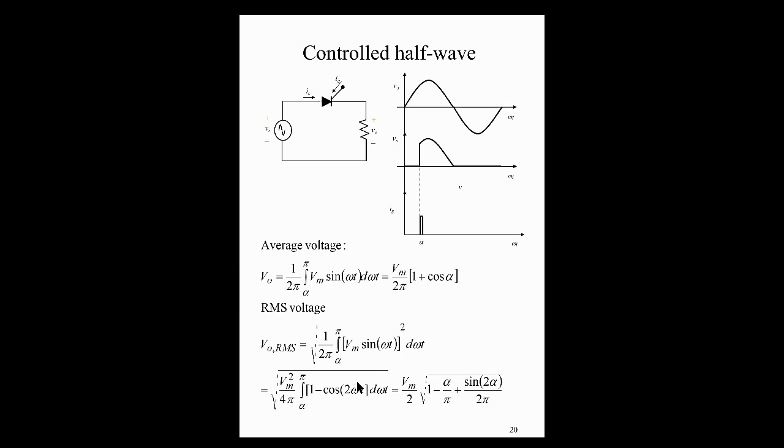However, with this circuit, resistive, inductive, we observe a negative spike that goes to zero right at the extinction angle. This negative spike is as a result of the inductor in the circuit. The inductive behavior will resist or oppose changes. So as that voltage decreases, that negative spike is in response to that change that is taking place in the circuit.